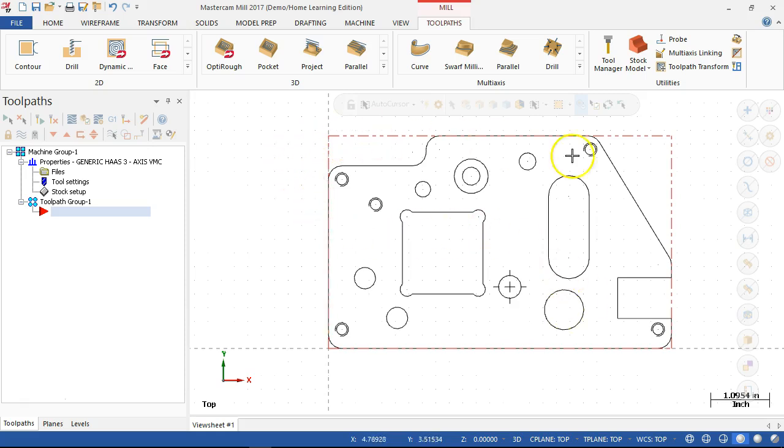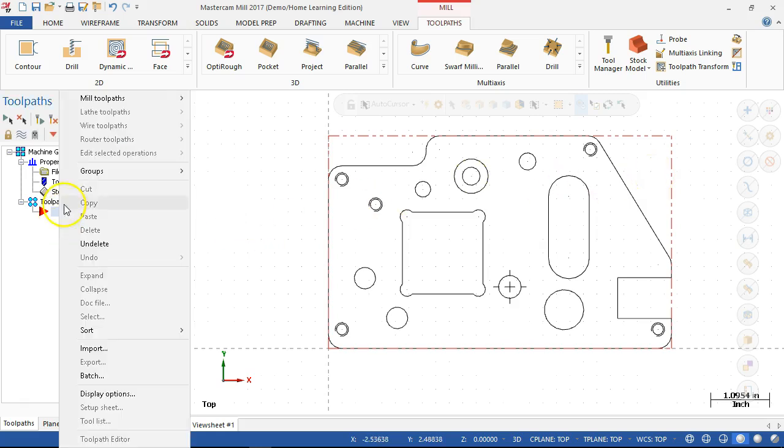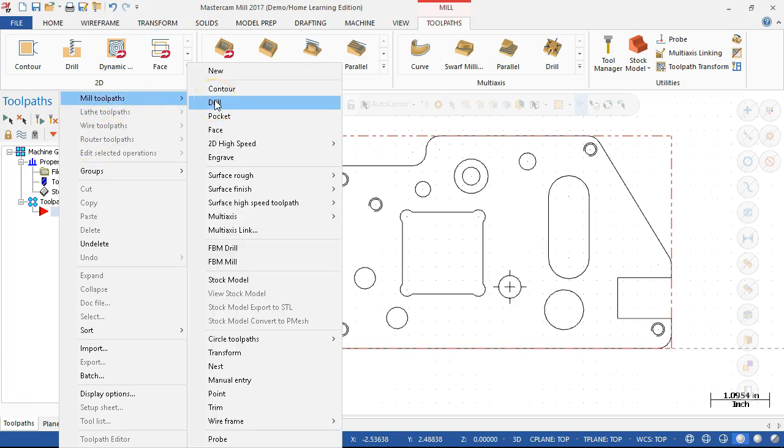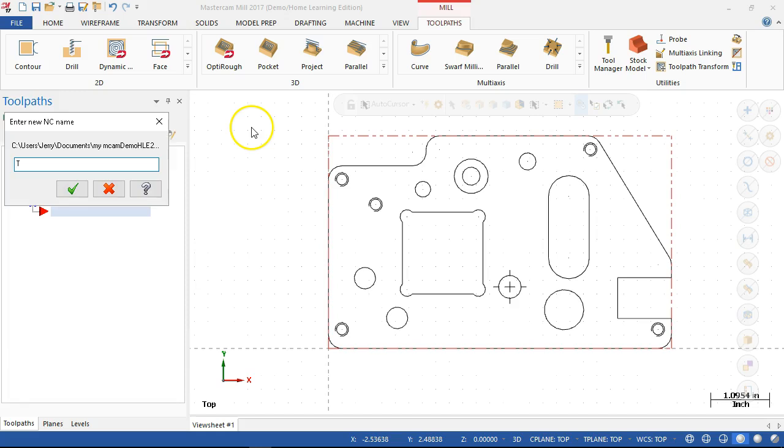All right, so facing operation, if we need it, is going to be our first group. And are we going with the large face end mill, or one of the smaller end mills running back and forth? The issue is, do I have one? Do I have a large enough facing mill to take this in one pass, so a 4 or 5 inch wide? Well, probably not. But a 2 inch, maybe a 3 inch is probably approachable.